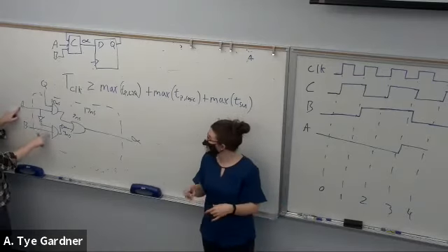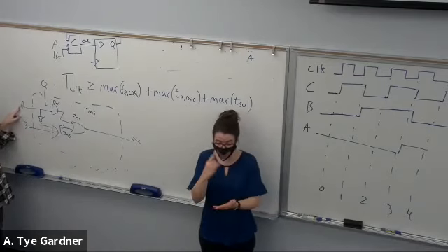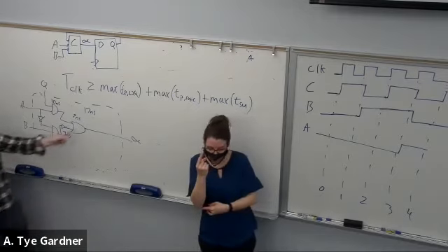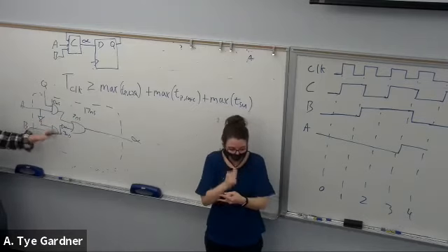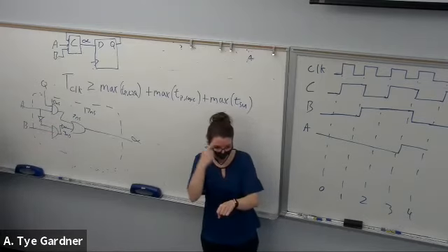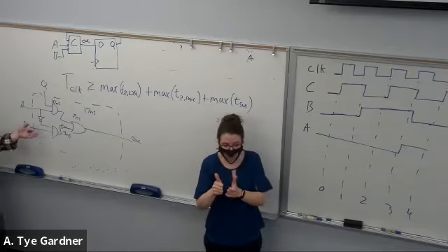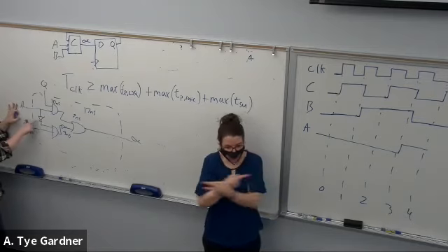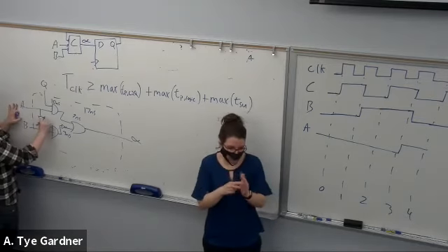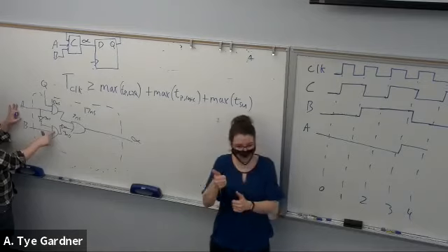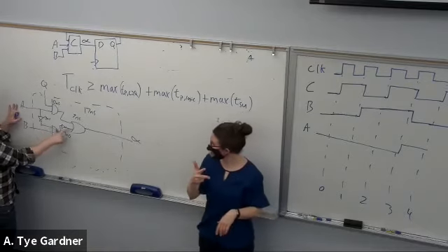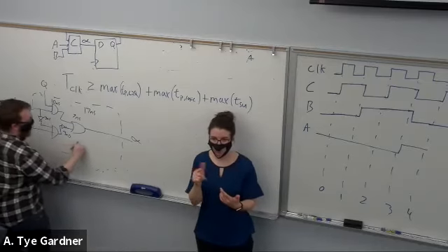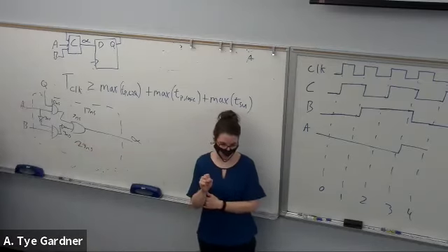This path through the inverters looks like probably the longest to me, right? Because it has the most gates. Now, having the most gates doesn't necessarily mean it's going to be the longest, because OR gates are faster than AND in this case, and inverters are faster than the others. So if we had 4 inverters, it has the most gates, but wouldn't be slower than even Q. Just a silly example. But here I'd have 3 nanoseconds on the inverter, plus 10 nanoseconds on the AND gate, plus 3 nanoseconds on the second inverter, and 7 on that. So 10, 13, 23 nanoseconds is my longest delay path.